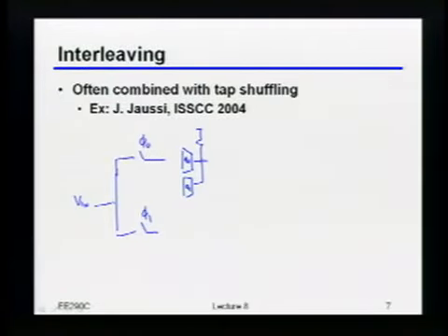So basically what I would have here is, for this filter, which is conceptually running off of the first clock phase, let's say that I want essentially the data and its first post cursor, right? Then what that implies is that, and I'll just draw the clocks here, phi 0 and phi 1. So phi 0 maybe looks like this.